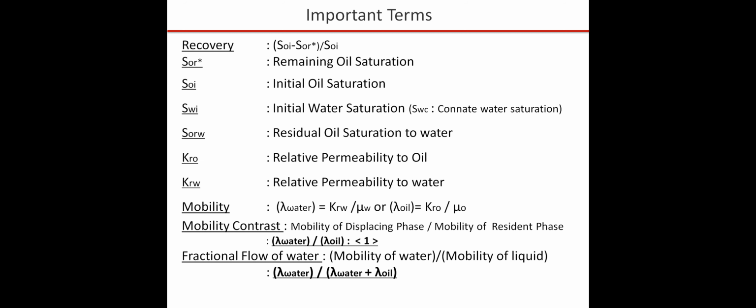So here recovery has been defined as the change in saturation of oil with respect to the initial oil saturation. SOR, I don't term it as a residual oil saturation because with every time step, the oil saturation is changing and it is the remaining oil saturation at that instant. It is yet to reach the residual oil saturation at the end of water flood.